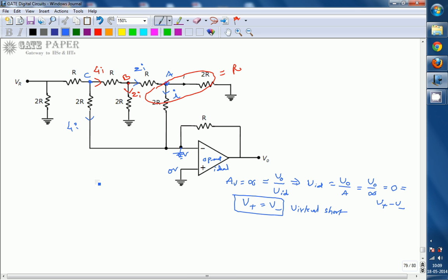Okay, because the effective resistance in the above branch and this branch is going to be the same, 2R, the voltage is the same, the resistance is the same, so you will get the same currents in both branches. So 4I, the total is nothing but 8I, which is the current flowing through this R. This one is nothing but 8I. And again the same thing is going to take place. The effective resistance is the same, so the current coming from this one is nothing but 16I.